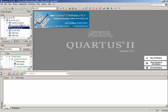Then we have the exponent part, which is just an addition of the two exponents, subtracting the bias and taking into account whether the multiplication generates a normalization or not, a rounding or not. We also have a unit in charge of checking exceptions, for example -0, 0, or not a number.